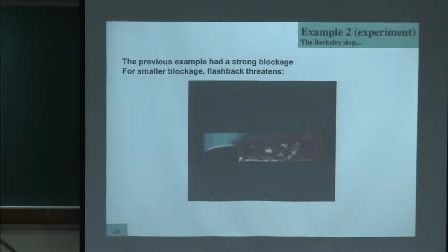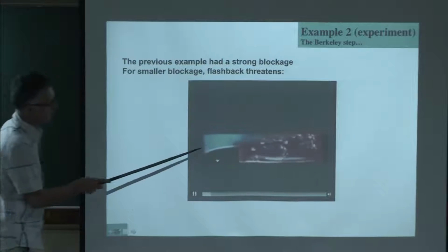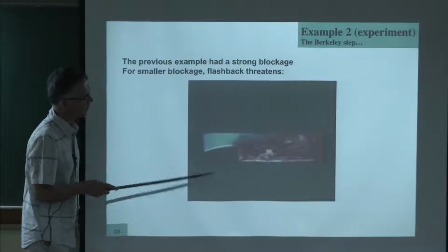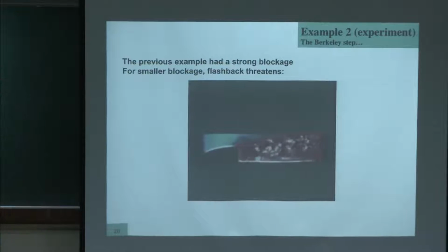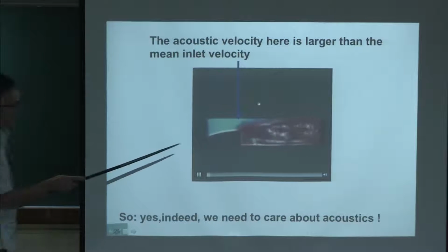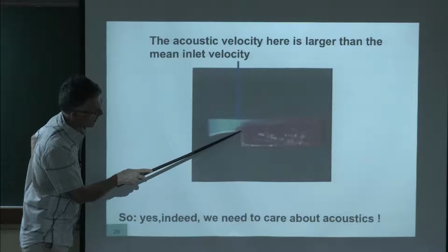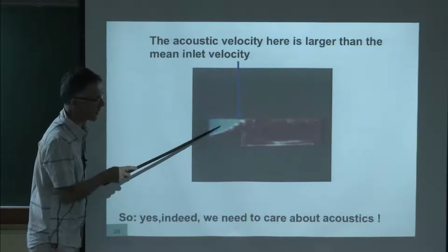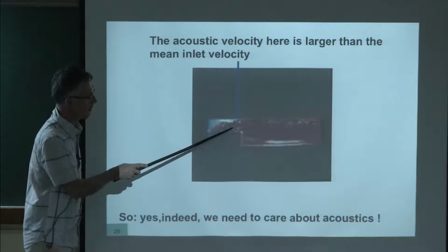Now it can go even more. You remember this movie I've shown you. In that case, you can have flashback here because the mean velocity here is less than the acoustic velocity. And if this happens, when you see the flashback, like now, shoop, it really means that you have the mean flow in this direction, the acoustic velocity in the other direction, and the flame is just carried.